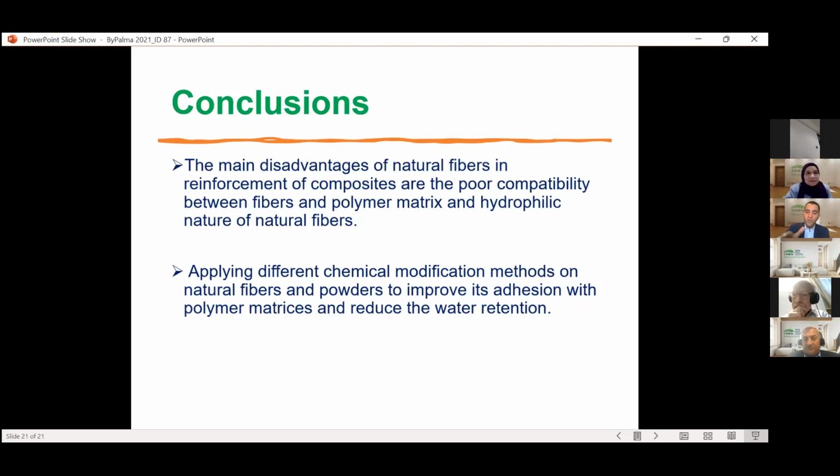After the carding and the laying of the bat, it goes into an oven, so that only the low melting temperature polyester fibers melt, and bind the natural fibers together to give some integrity to the non-woven insulation bat. So this is one thing that perhaps could be considered, the textile processing.